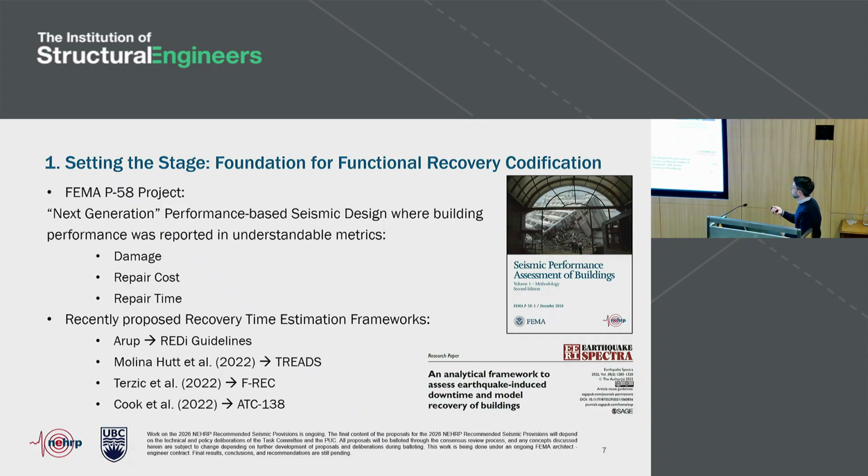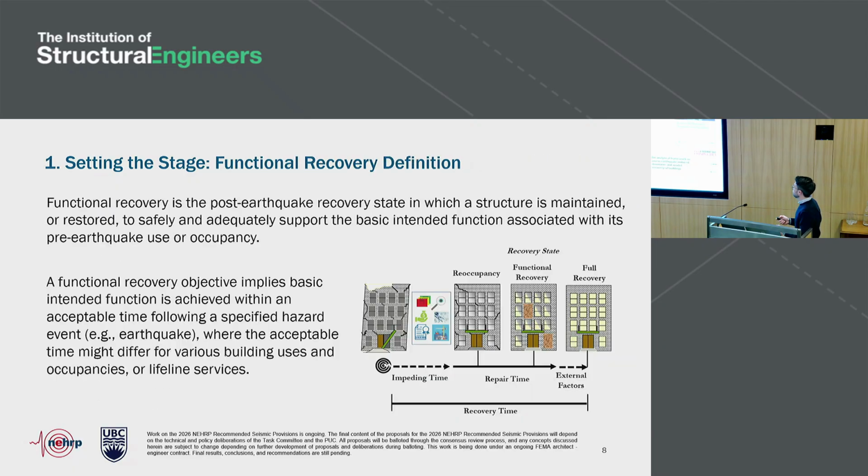And more recently, there have been a number of studies, like my students and I published this framework called TREADS, or Tool for Recovery Estimation and Downtime Simulation of Buildings, and there's a paper associated with that and code available online. Vesna Tursik and her students published this framework called EFREC, and Dustin Cook, Abilal, and others published another framework that was recently adopted by this new project, ATC 138, that will also be released very, very soon, that essentially takes FEMA P58 and extends it to do assessments of functional recovery time. And that is what we used in this work to develop these new provisions for functional recovery performance.